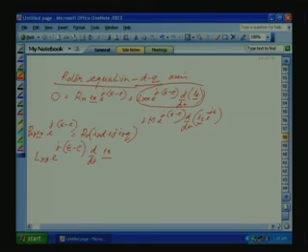See, this IR is originally defined with respect to the rotor axis. Now, both the stator and the rotor axis we defined with respect to the stator alpha beta axis. That is why we have multiplied outside by e raised to j epsilon. Now, the whole equation we are transferring to the general rotating reference frame. That is why we are multiplying by e raised to minus j rho.